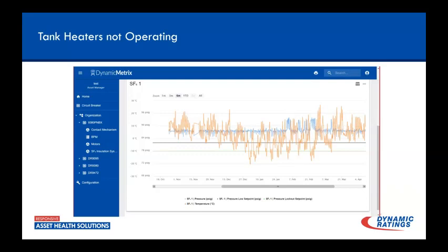But you need to understand, especially when tank heaters are involved, if we top this off and we do it up to a higher pressure, so say 82 is nominal, we go up to 86. Now we are putting 96 when the tank heaters come on. Now, suppose our thermostat goes bad and tank heaters stay on, well, now in the summertime, we're going to blow a rupture disc on this breaker,